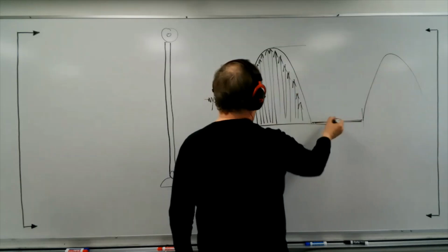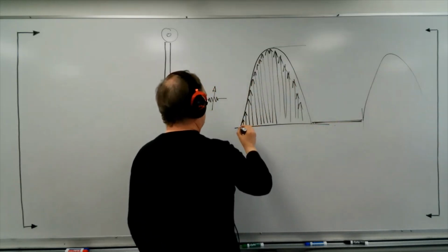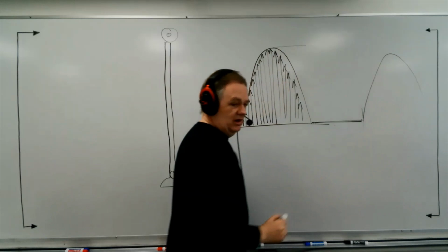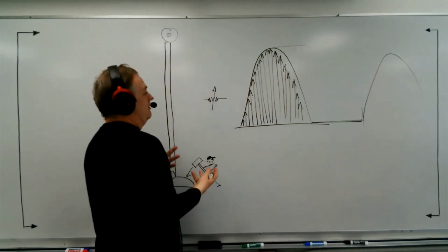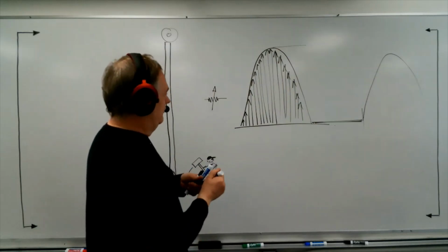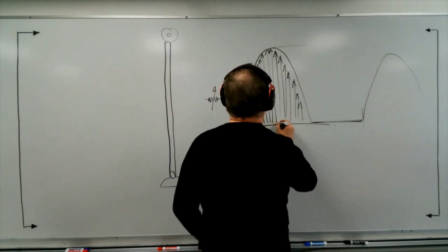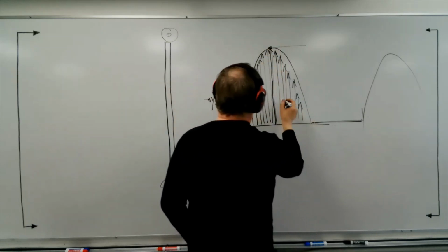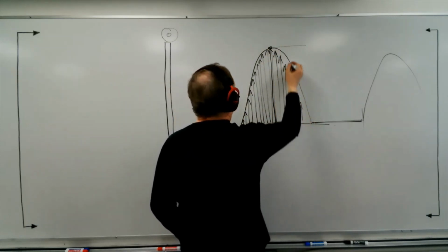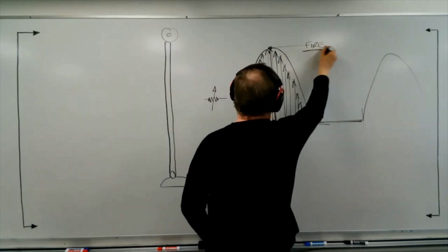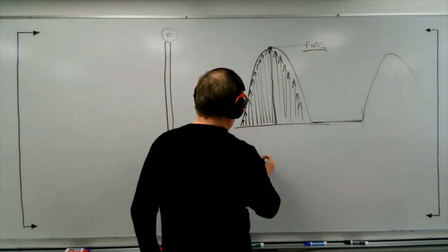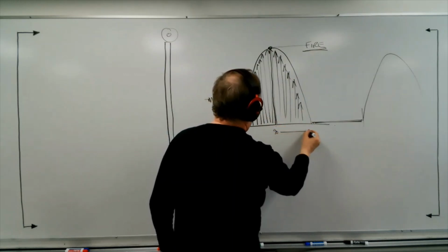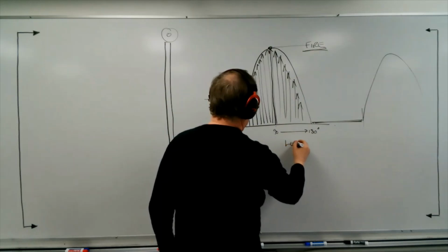Now, if you don't change the resistance in between here, all that happens is your current will keep going up to a maximum value and back down, dead space, up to a maximum value and back down, another dead space. And so you don't fire the SCR, you don't ring the bell, doesn't work. And so if you fire by 90 degrees, then you have success, okay? Now the rest of these pulses will still enter the gate, but as long as you actually fire by here, then your SCR will give you voltage. It'll be closed and the load will have voltage from 90 to 180 degrees. You will have load voltage.